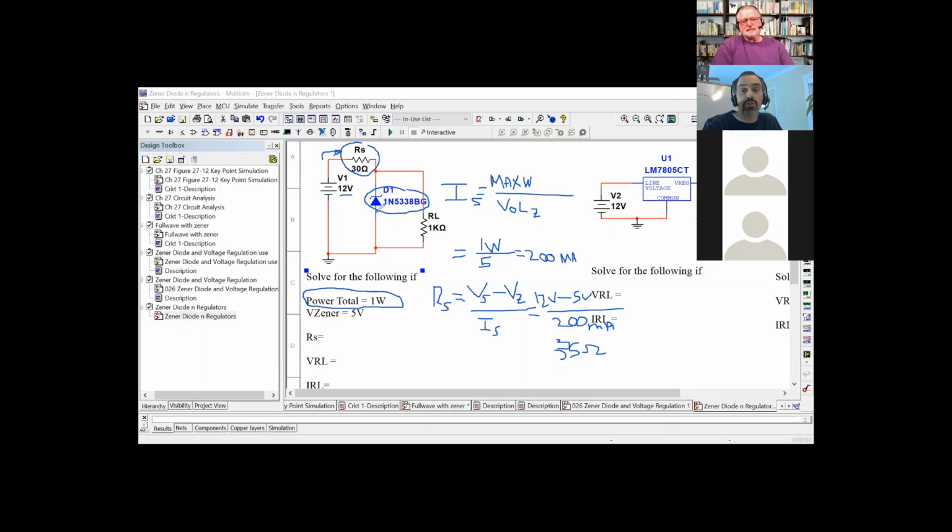You could go to Mouser Electronics and pick up a Zener. You Google it, and you're going to come up with 10,000 different values for a Zener. And you're going to be like, well, great, which one do I want to use? The biggest thing, anytime you have to replace a Zener, is that number one, you want to make sure you get the correct voltage. Always the correct voltage. It doesn't matter on the current.